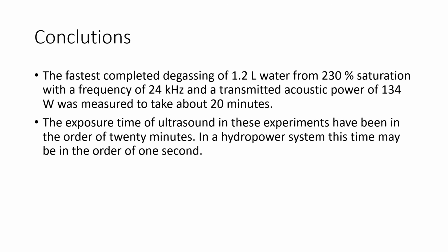The next point is the exposure time of the ultrasound in these experiments. It's been in the order of 20 minutes. In a hydropower plant, you would get down to in the order of 1 second of possible exposure time. So this is going to be a challenge. You might need to increase the power to increase the degassing efficiency. But this also needs to be tested in maybe a small scale model.